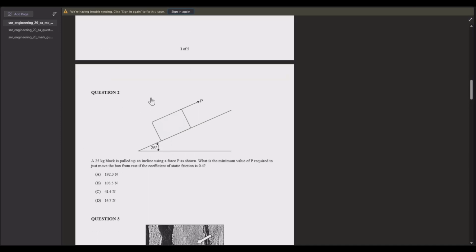And then this is just your basic incline slope now. From the IA3, this formula is pretty well burnt into my head. Let me write it down. So this formula here, it's not the one I'm going to be using here, because if we're going down a slope, the force here is going to be equal to this, but if we're finding the force required to go up a slope, we're not going to have that minus, instead we're actually going to have a plus here, because it's inclusive of that frictional part that we need to overcome.